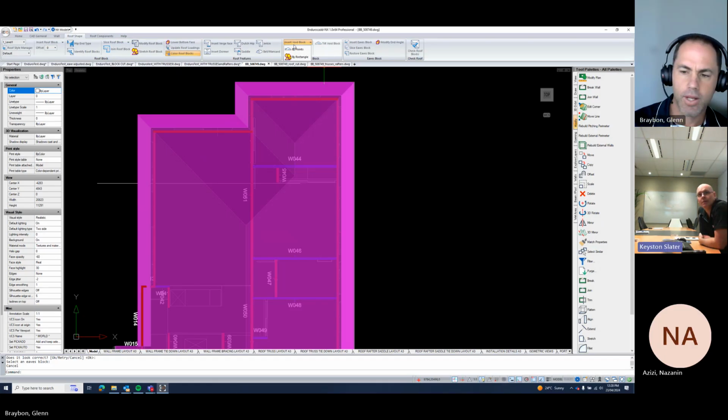Yeah, I found that a bit glitchy when I tried that. It was a bit funny. The end result was always kind of similar, but there were some options there. With the ceiling block, it's harder to adjust the bottom face because it stays at the ceiling level. Whereas a void block, you can adjust the bottom face to any position.